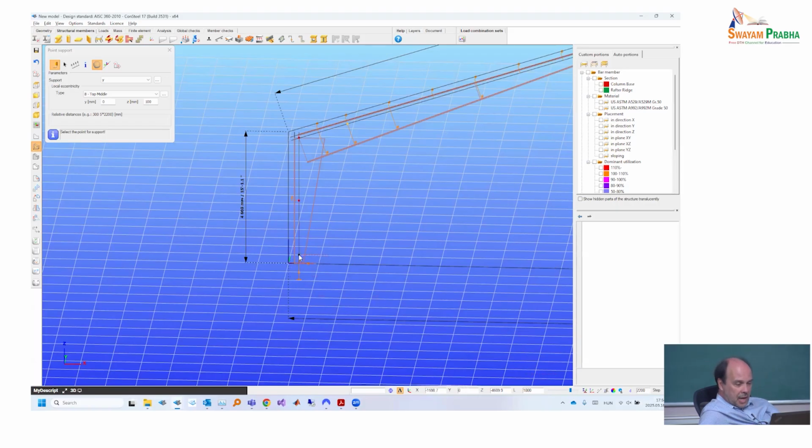And it's always important to start right. If a line is maybe 3,000 millimeter long and I say 2,000, obviously if I start from this end, then 2,000 will be here, and there will be another 1,000 from here. If I start from this direction, then there will be 2,000 and 1,000. Consteel will always place the position starting the line from the end, which is closer to my actual position of my mouse cursor. Okay, so that's why I always approach my mouse to the line of the object from which I want the measurement to be made. So that's why I always came close to the line from below, and then the point appears.